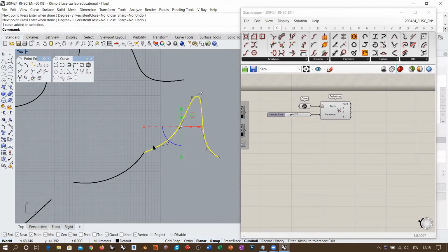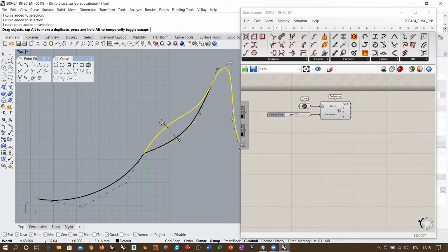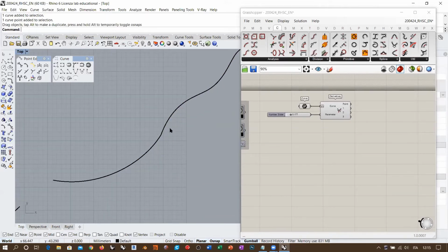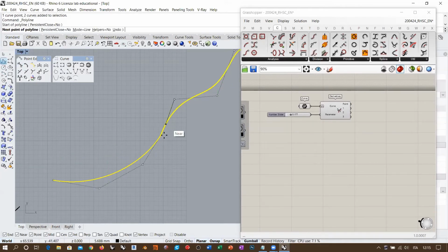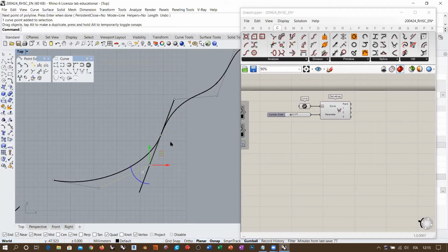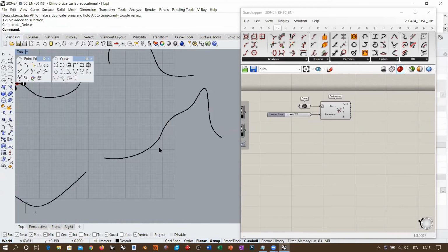And I want this control point curve to be tangent to this one. So let's say that this curve has this tangency. I want to make sure that these two curves don't form any vertex here. So I take this construction line here and place this point on the path of this line, so I'm sure that now there is no vertex in this point.